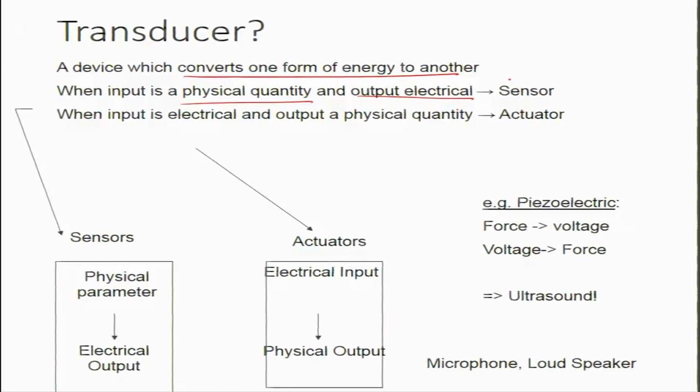If we are talking about a sensor, typically all the inputs are in the physical domain and the outputs are in the electrical domain, but it could be the other way around as well. If it is an actuator, then there is another conversion: you give it an electrical or maybe an optical signal, and the output is always a physical quantity in terms of a motion, in terms of displacement, relative displacement, and so forth. So that's in principle the conversion process of one form into another.